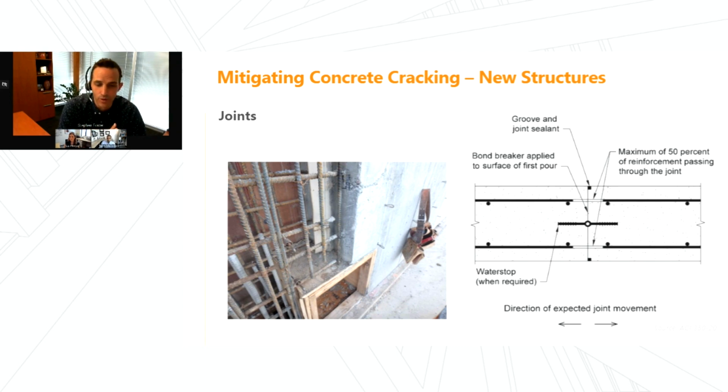The protective coatings are going to be a long-term maintenance item. Again, kind of sacrificial. It's there to protect the concrete and the reinforcing behind it, but over time that'll eventually need to be replaced. And so in my experience on new structures, the cast-in liners, if it is an aggressive environment, those are used probably more commonly than a liquid applied coating. But again, it will also depend on the chemical environment as well. And the more aggressive conditions, maybe it leans more towards some of the liners.